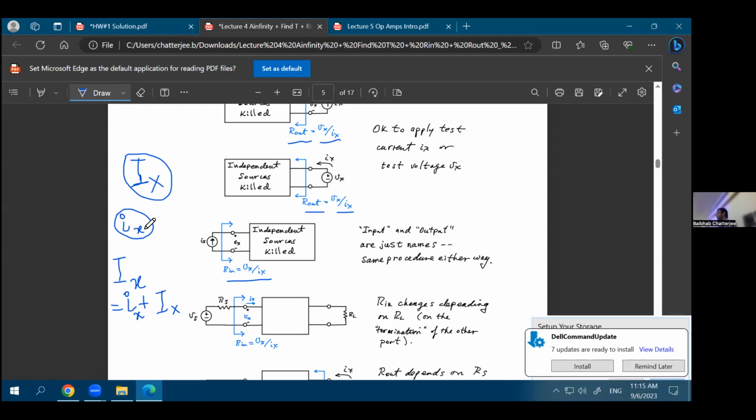So don't get confused between these three different terms. A lowercase definition always means that it's an AC quantity. An uppercase definition means it's a DC quantity. And when you have a combination of uppercase and lowercase, it means both are present. And you might have already guessed that the purpose of this DC quantity is just biasing.